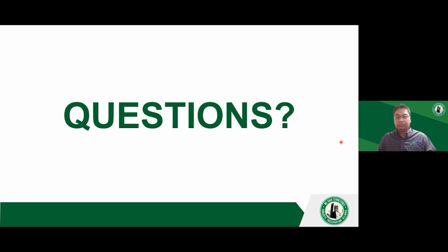No, very good. I think that's a very good explanation. Yeah. And going back to GPR, this person asks about the test method. It can supposedly detect rebar corrosion activity before concrete damage occurs. Speaking of GPR, is there anything GPR does to detect the corrosion activity of that reinforcing steel when you're looking at it? No, you cannot.